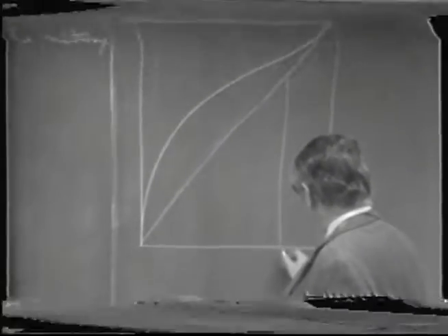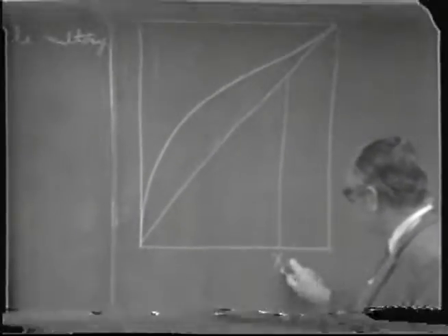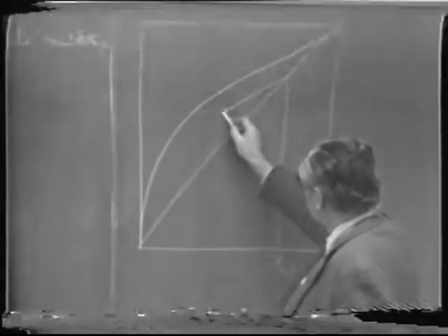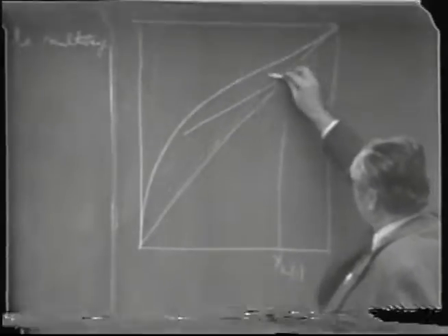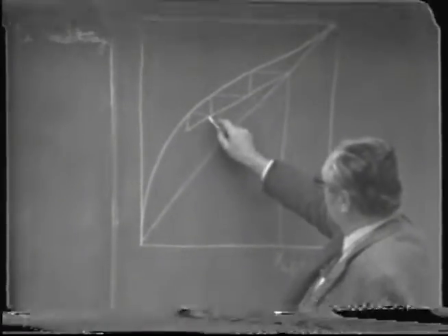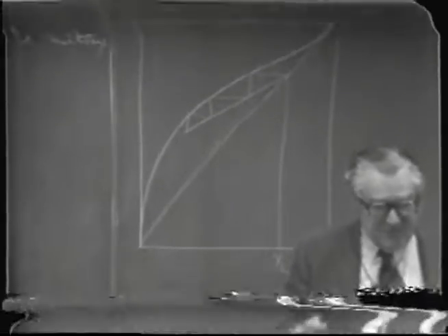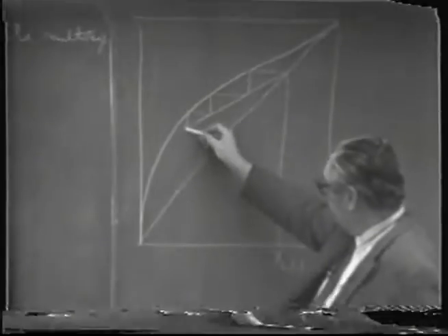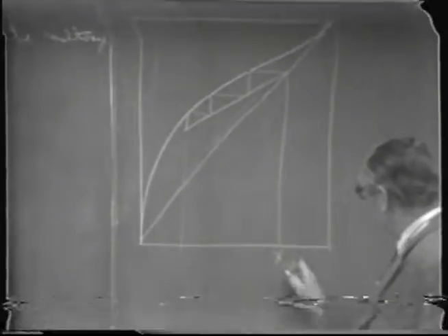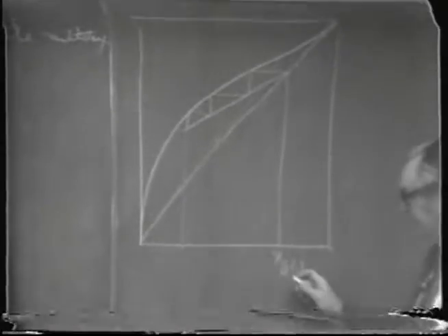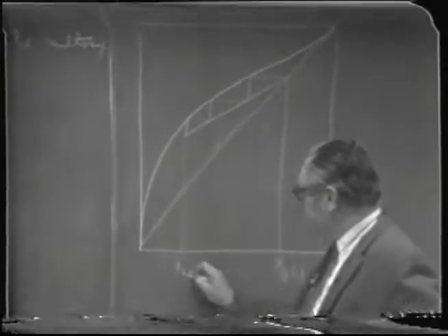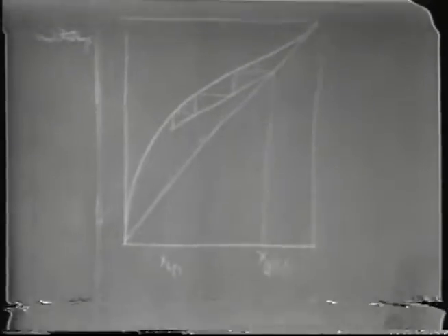If we started at any particular time, if this was the concentration in the pot, X sub L, let's say state 1, at a given reflux ratio, we could, by stepwise manipulations, determine, let's say if we had 1, 2, 3 equilibrium stages in the column, that this would be the, I should have said this X of distillate, X of D. If this is the initial distillate you were going to expect to get, this is the initial X sub L in the pot, which would produce that, at any moment in time.